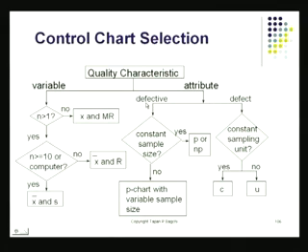For attributes, if it is defectives, you go to the P chart or the NP chart. N is your sample size. And in that case, I could probably do this without much trouble at all. Something that is important for the P chart is your sample size need not be the same, because the control limit itself has n built in there. So in fact, if you go back to the formula that has the P chart there, the P chart will show you that sample to sample there may be a change in sample size, and you will have no problem at all. Use them as if the charts are like the old 3 sigma up and down type of control chart.